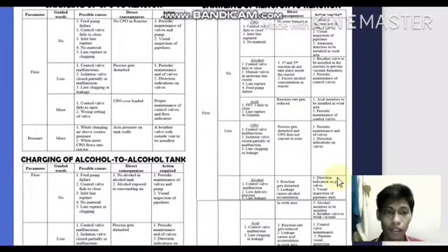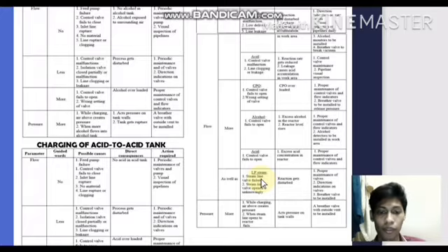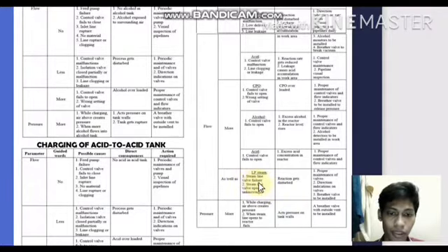Okay, sorry, so I want to tell you about this section, which is for low pressure steam. As I told you before, steam is the heat source to make the esterification process faster. So if the steam line valve fails, or the steam line valve opens unknowingly, that means the process for esterification becomes slower.